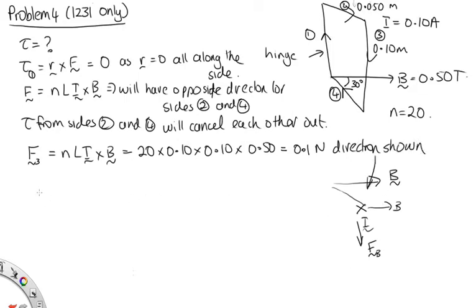Down there. Okay, so now the torque is equal to r cross F. So r is the vector drawn from the pivot point to where the force is applied. So that is our r vector and this is our F vector. That in there is the 30 degrees. So this here is 60 degrees. There's an angle of 60 degrees between them.